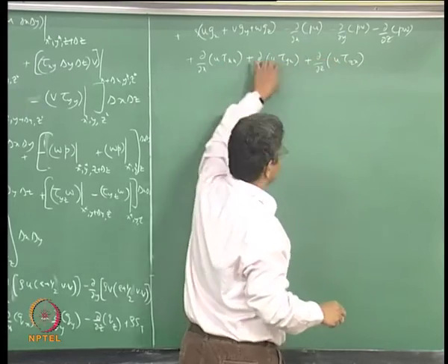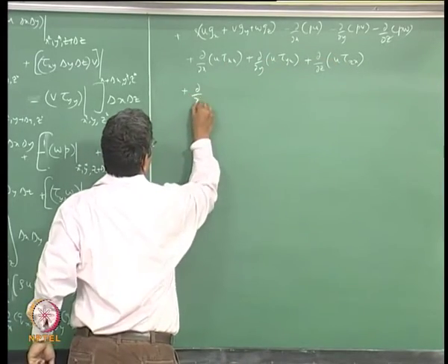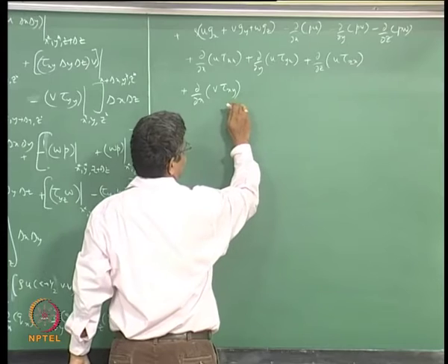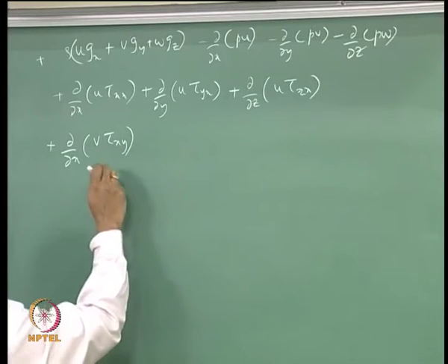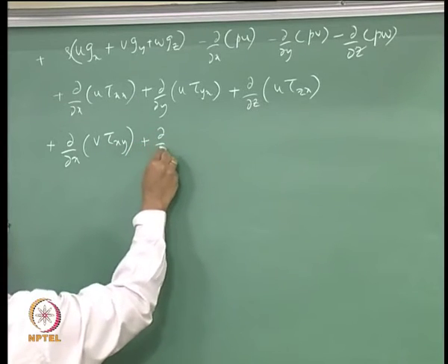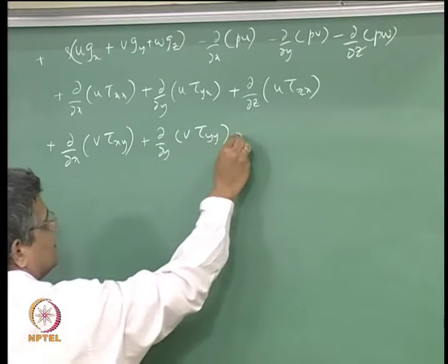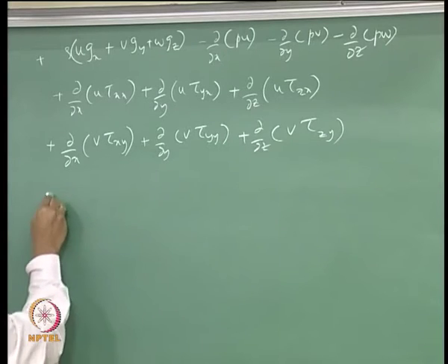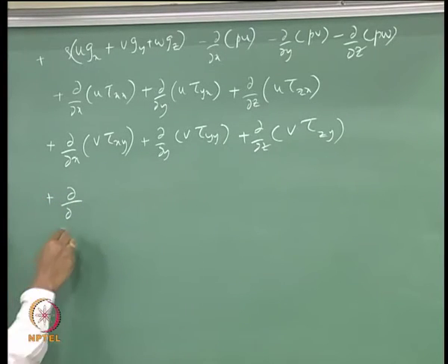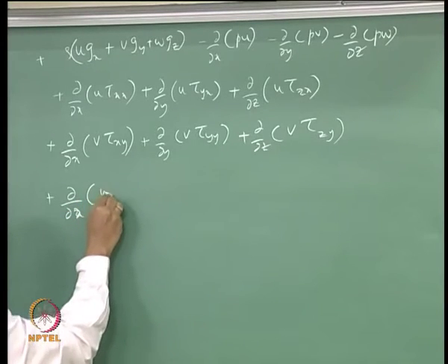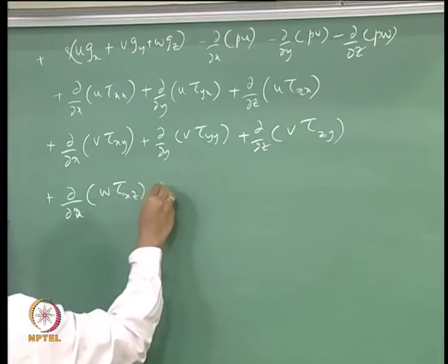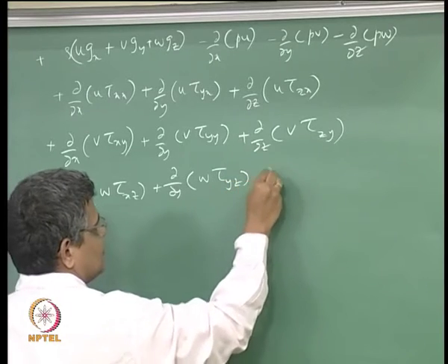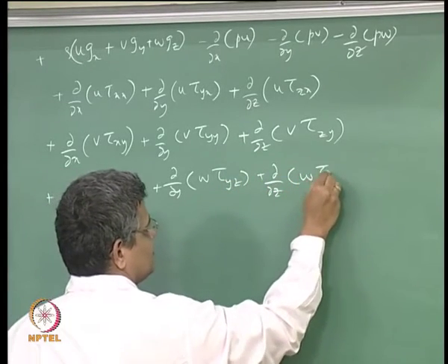Contributions coming from the stresses acting in the x direction, and we can similarly write ∂/∂x of (v τxy), that is, stress acting on the y face in the x direction, plus ∂/∂y of (v τyy) plus ∂/∂z of (v τzy), plus stresses acting in the z direction: ∂/∂x of (w τxz) plus ∂/∂y of (w τyz) plus ∂/∂z of (w τzz).